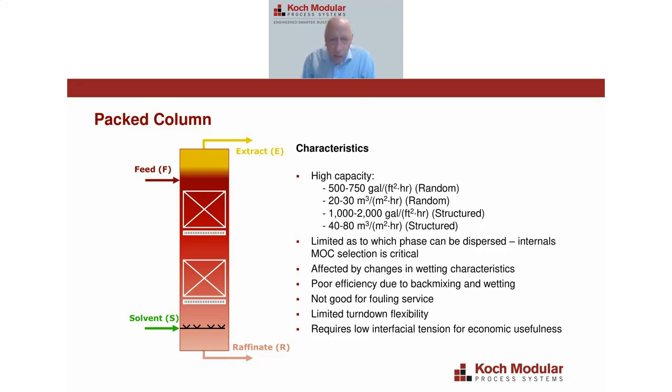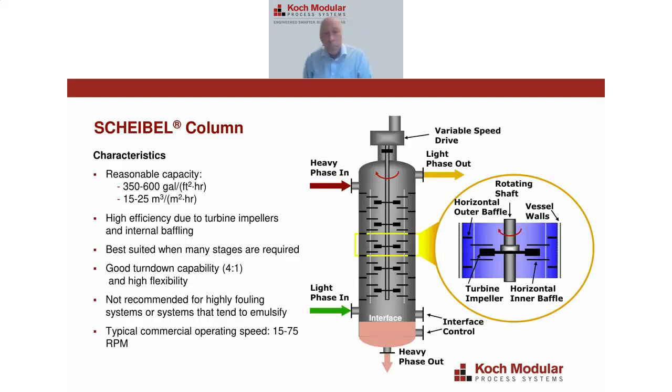So packed columns are not good for fouling services, and they have somewhat limited turn down flexibility. Also, they tend to be best for low interfacial tension systems, not high interfacial tension systems.